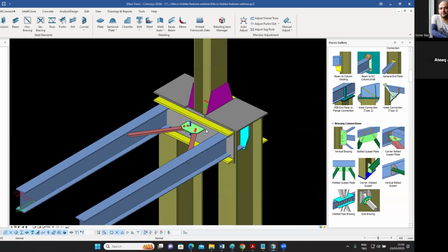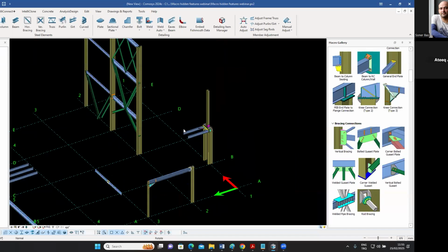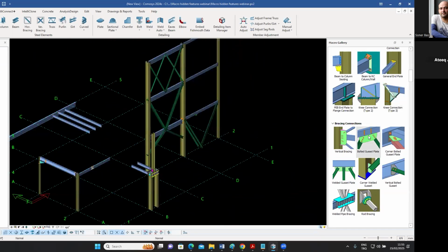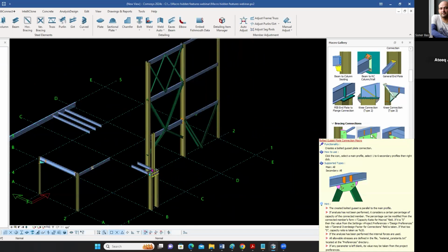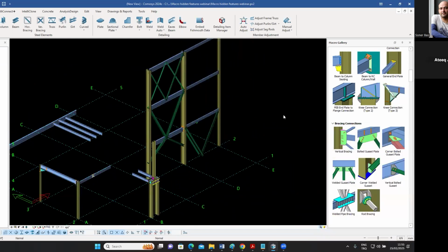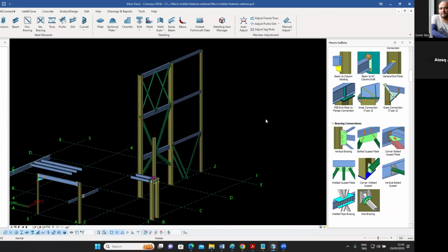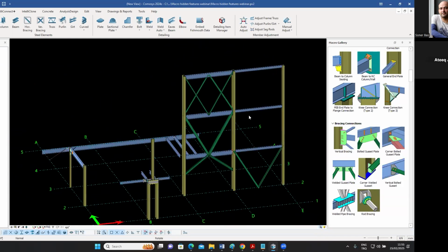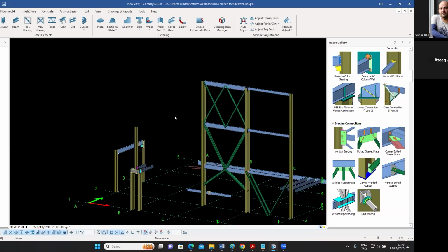Now I want to show you a few examples which are also kind of hidden, in the sense that people think the bolted gusset macro will typically work for angles. But there are many other cases for which we can use this macro. So let me start off with eye sections. So here is an example of an eye section.